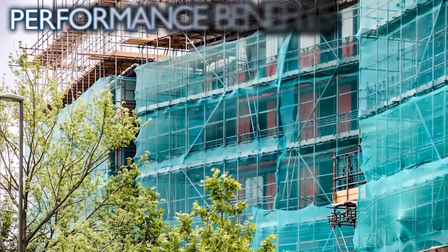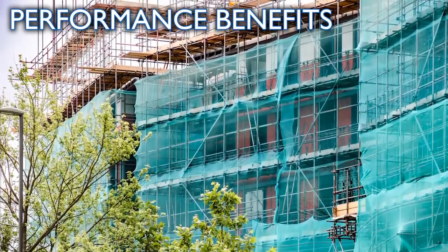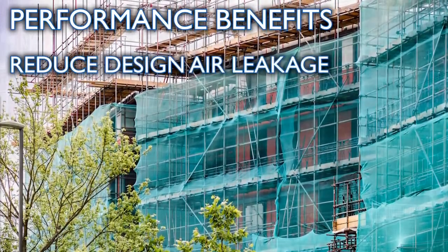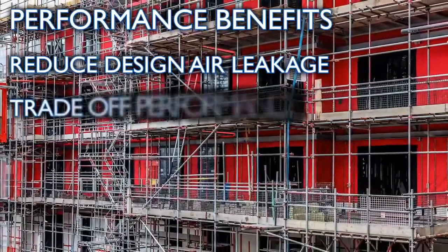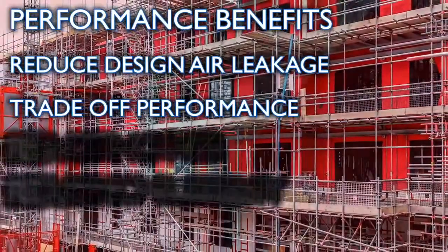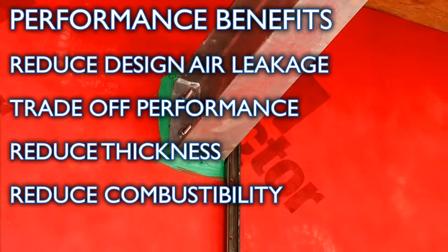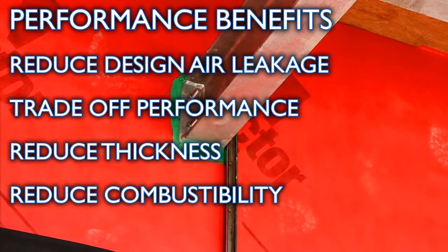So now let's consider the benefits of this more reliable air leakage performance. If we can be sure we'll achieve a low rate of air leakage, then we can reduce the design air leakage rate used in our modelling, which means we can reduce our requirements in other areas. In a recent project we were involved in, this improvement in air leakage was traded off against the fabric insulation. In this case, however, the goal was not to reduce the thickness, but to switch from a rigid foam insulation to a less combustible mineral fibre product.